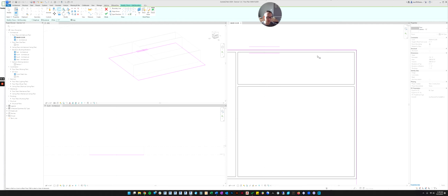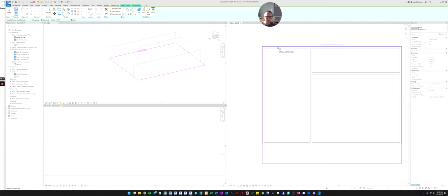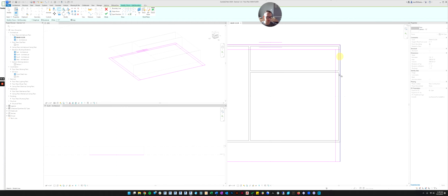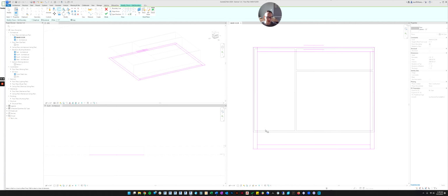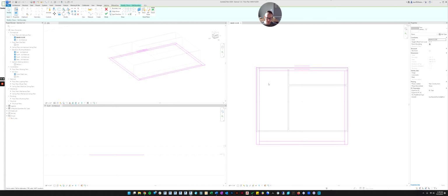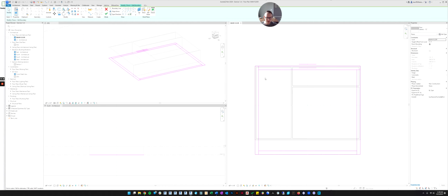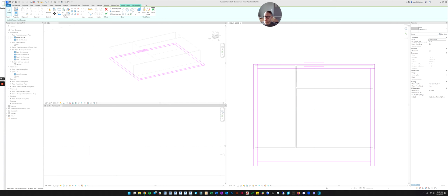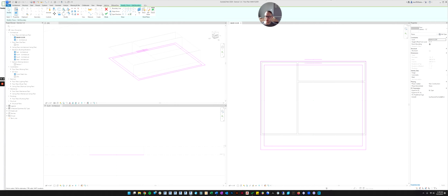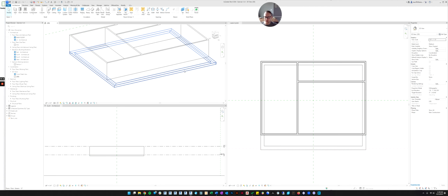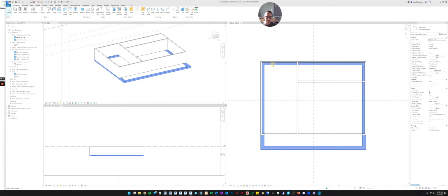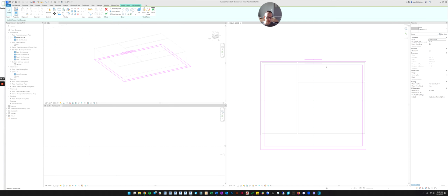And now if I go to the sketch, you can see if I highlight something, there's that little blue line that's offset 2 feet. So now if I wanted to, for some reason, create a floor that was donut shaped or that didn't have a center part, that's how I would do it. And then we could use the trim command to get these corners right. And then we could finish the sketch and you can see how it's made a funny floor. So let's go back into that sketch, edit it, and undo what we just did.